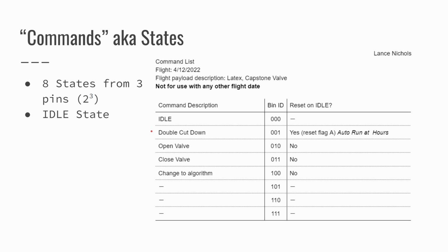That's kind of the whole point of this presentation, that you really need to understand this. The idle. For example, if you send cut down and then you immediately send idle again, there's no guarantee that this will get interpreted in time. It might just get immediately set back to 0, 0. So for a millisecond it might be 1 and now it's 0 again, and then it might not see it, right?